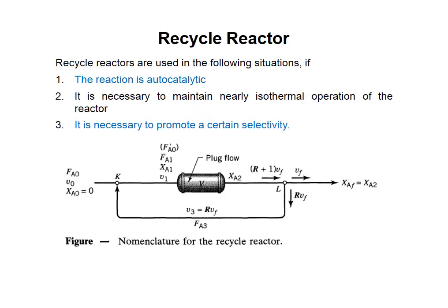So what is a recycle reactor? Recycle reactors are used in the following situations. First, the reaction is autocatalytic. Second, it is necessary to maintain isothermal operation of the reactor. Third, it is necessary to promote a certain selectivity.